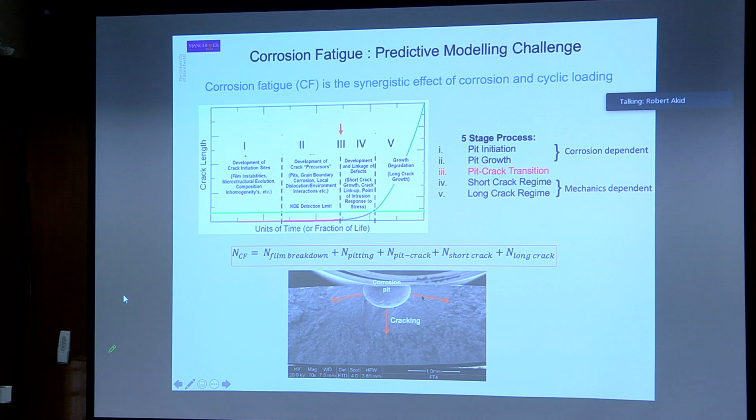So yeah, sorry, I probably should have had an extra image on here to show what we've seen in some of our studies. Your comment on the profile of the crack is absolutely correct. One of the things that we did was we did not try and use any mechanically deformed pits, i.e. from drilling or from electro discharge machining, because they're not representative at all of the pits.